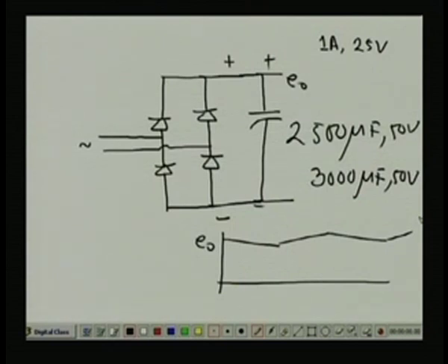The best filter for this power line filter is a pi section filter. That means you use a capacitor, inductor, capacitor like this one, right. But L is no more used because L has a lot of associated problems, magnetic field, and it is costly, it is bulky. So, to avoid that, people use a simple capacitor of higher and higher value.